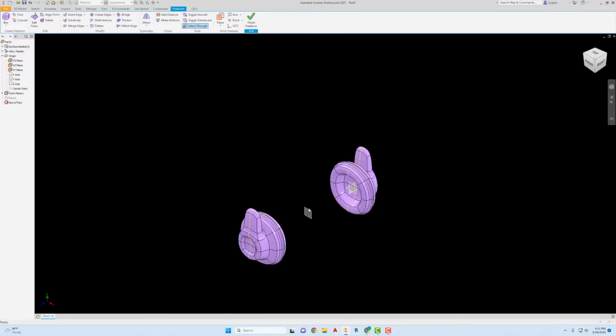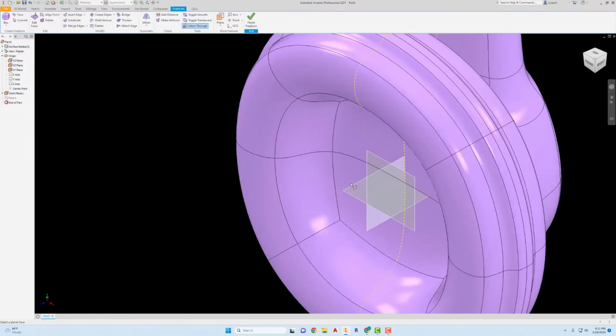And then what I want to do now is create the headband part that curves around. To figure out where that needs to go, I'm going to make another offset plane. But this time I'm going to offset this horizontal, this X and Z plane. I'll zoom in here, you can see which one, this one here.